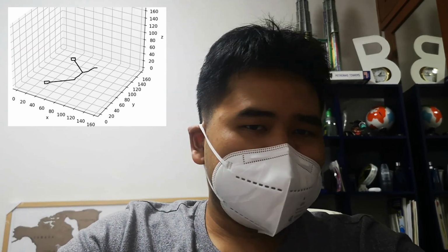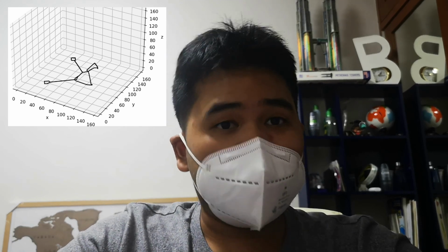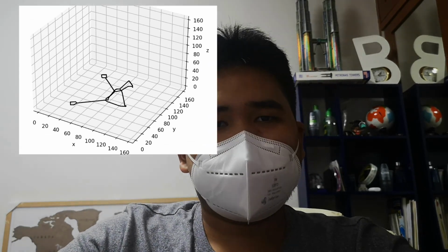Now that we have this information, how can we translate it to the useful G-code our machine needs? We simply project our 2D points to our 3D mesh. This is done by finding an intersection between a vector and a plane. From these 3D points, we can simply generate the G-code using the movements that follow the path traversal of our graph.